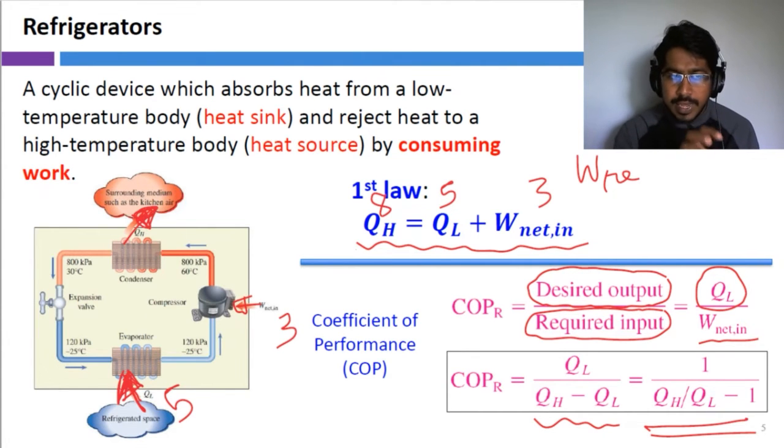You know what I mean? QH does not have directional information. So whether it is negative or positive, that's our responsibility. That is a very important point. QH and QL are scalar quantities, those are scalar values. The signs in front of them, positive or negative, indicate what we intend by them. Are we clear?